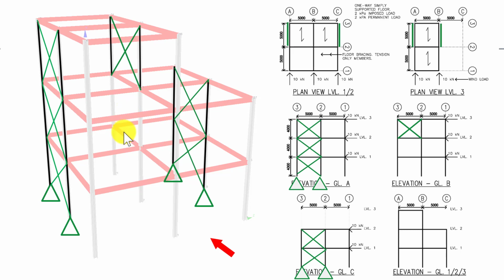However, it would block then the access on 2 floors and would probably get in the way of the structure's operation. So I want to keep bracing on the outside of the building as far as possible, so I'll rather go down and then carry the loads horizontally with floor bracing here and here.